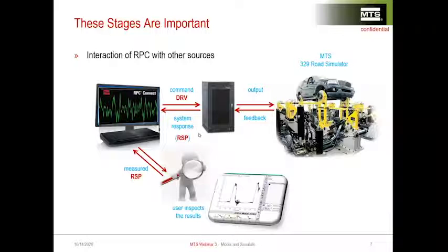So imagine we play out our simulate drive and then measure our simulate response. With the help of that data, we can calculate our FRF and hence use it to understand our system behavior, and that is the model stage, of course. And to recreate these scenarios we measured outside of the lab, we need to pass the well-known iteration process, which you are all familiar with, of course. During the iteration process, we have to analyze our data and inspect the results, and this is the simulate stage, of course.